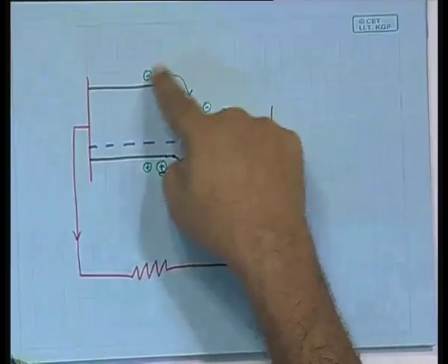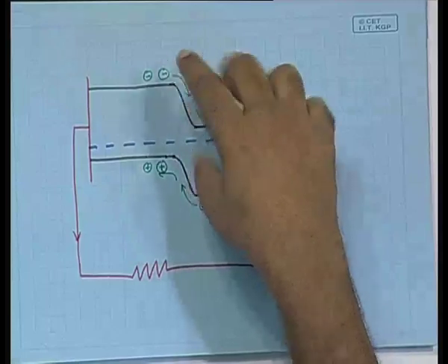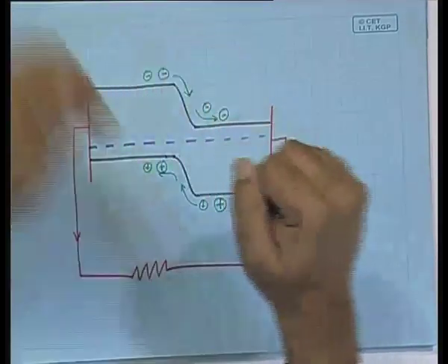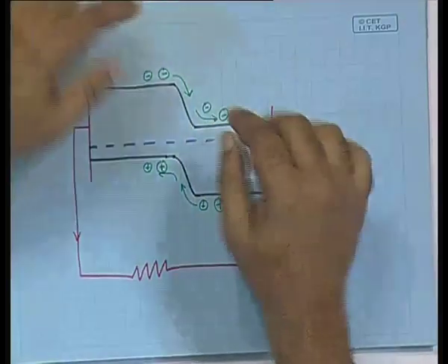So, unlike the normal p-n junction diode that you have come across, what additionally is here? The creation of the electron hole pair, and the electron hole pair has to be created close to the band bending region. Which means that a large amount of area has to be exposed to the sunlight and the whole p-n junction has to be over that area. Okay.